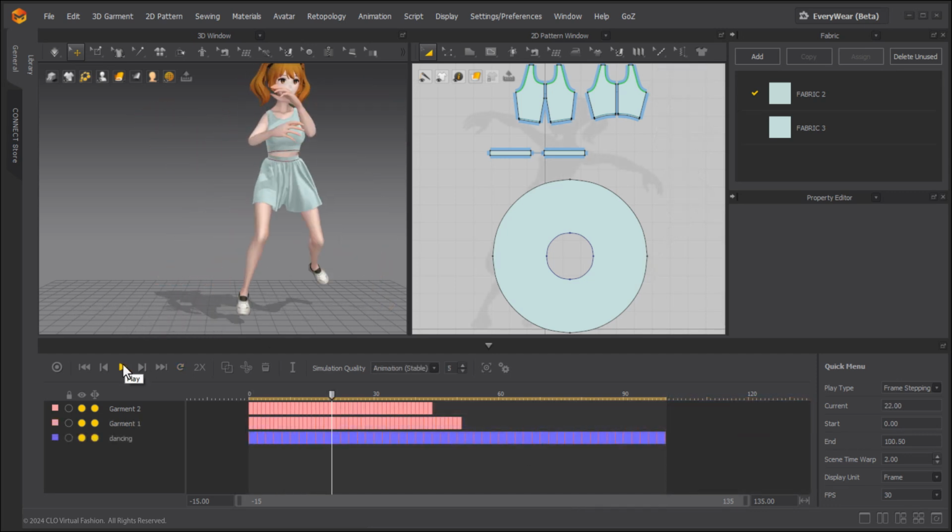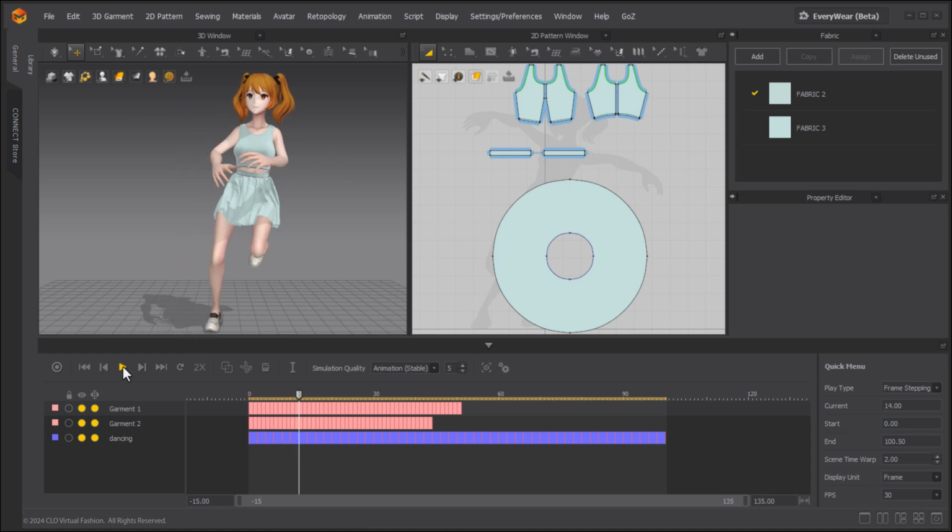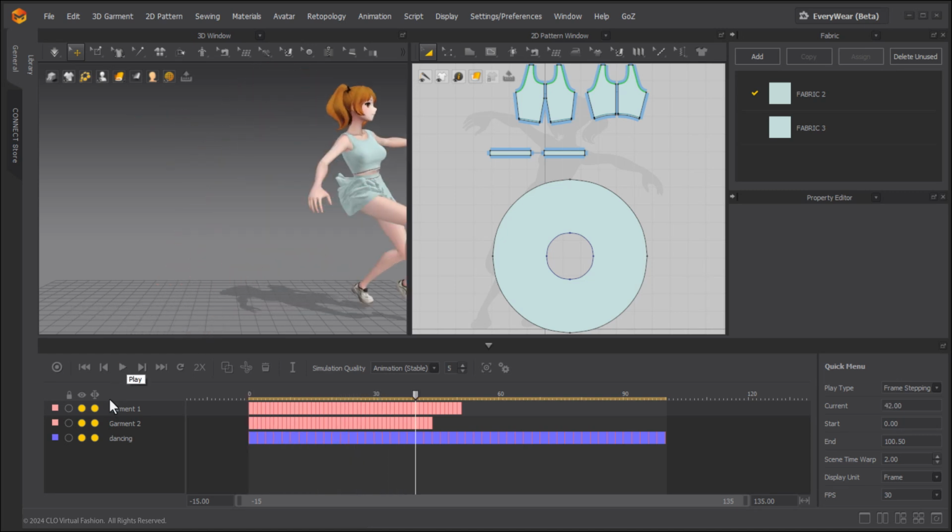If animation exists at the same frames in two animation layers, the keyframes from the top layer give priority. Animation layers can be reordered by clicking their title and dragging up or down. Animation layers can be moved horizontally by double-clicking to highlight them, then dragging them left or right.